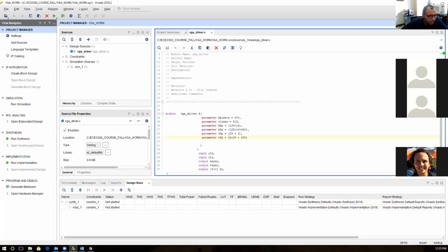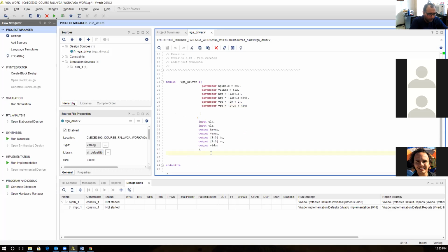Okay. So now what we can do, we need to go ahead and create the process of the whole entire thing. So what I'm gonna do, I'm gonna make some internal registers as we do before, you know, is always blocked as a procedure block, right? And everything gonna be clocked because we are working in a counter behavior. I need to see something going high like this, and I'm gonna be covering the whole entire display time in a horizontal. Then I will go down with front and back porch, and then I will go up again in a certain amount. Then I will keep doing the same thing over and over until I will cover the whole horizontal. Then I will start taking the second vertical and do this again horizontal many times.